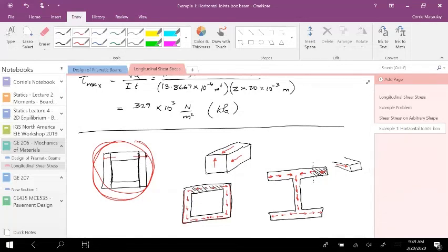Is that dependent on where the force load is? Would it have to be coming down on that shape? It's possible you could have a load right here, but the idea is if the load is anywhere on the beam, but you put that beam in bending, we're still going to have those longitudinal shear forces, and they're not necessarily only on that horizontal portion within the beam, but they're also on the vertical face of that beam, right?